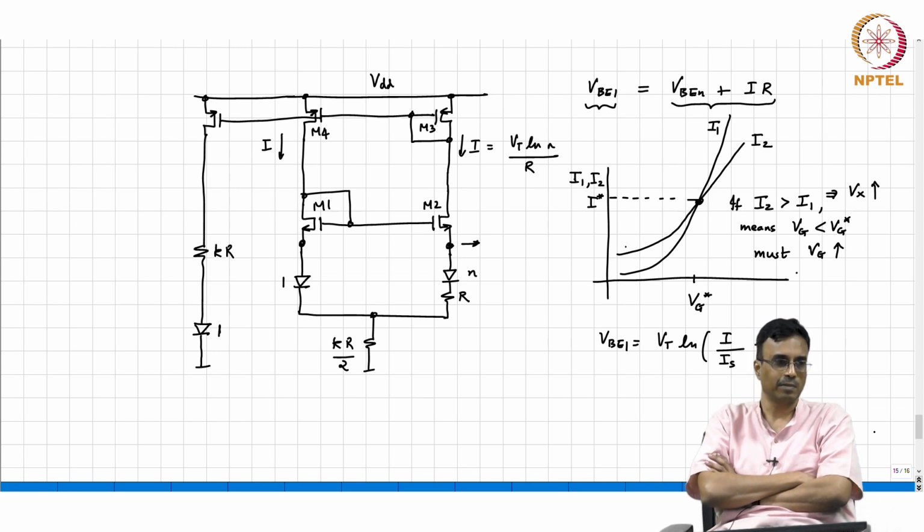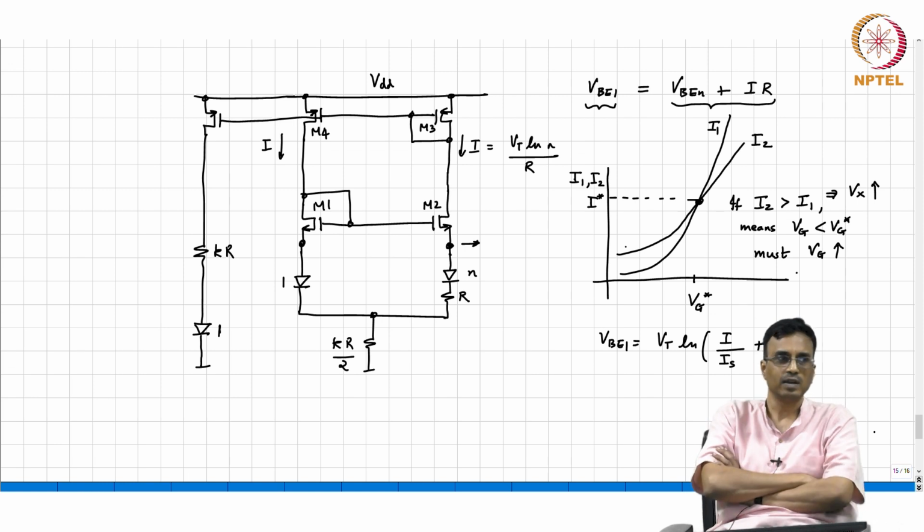So you pump the same current through a branch of size 1 and size n plus a resistor, and find when the voltage becomes the same, or apply the same voltage and measure the current and keep varying the voltage until the currents become the same. In either case, you will eventually end up with the circuits that you see, right?